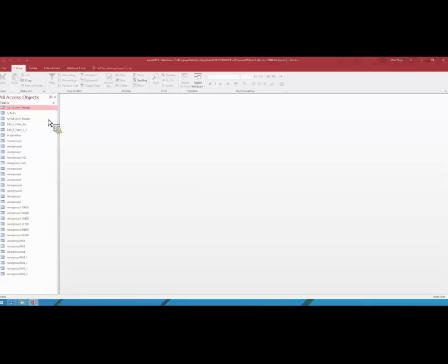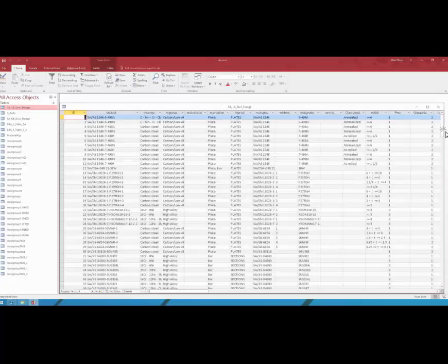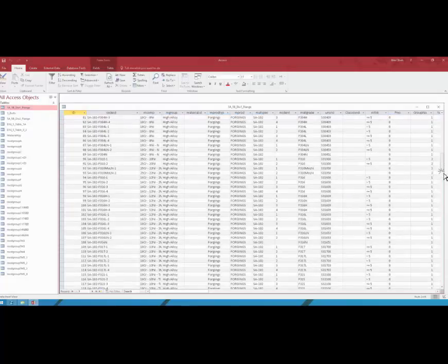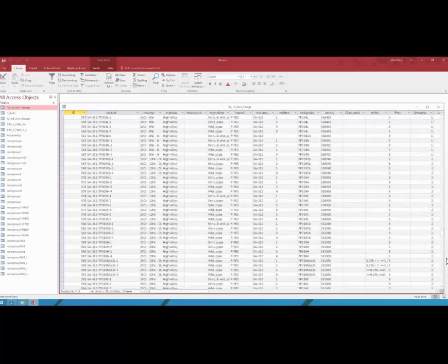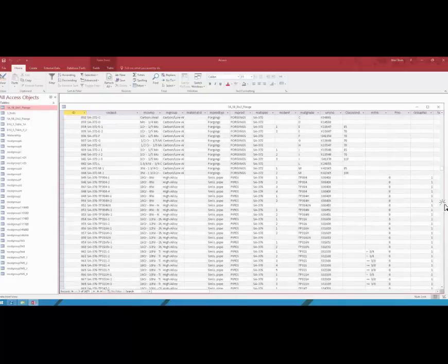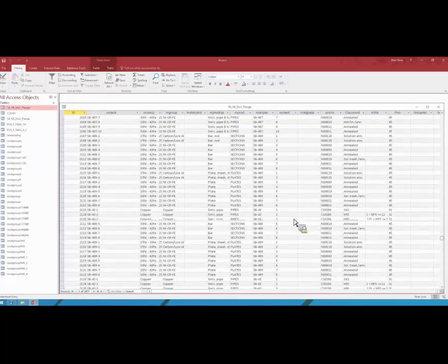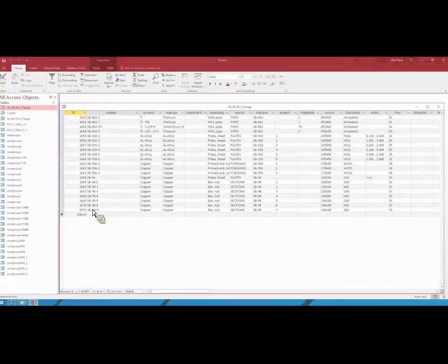And there you can actually see all these tables. For example, if I wanted to add another material, a flange material which is not available by default in these libraries, what I can do is go to the very end and enter a new record.